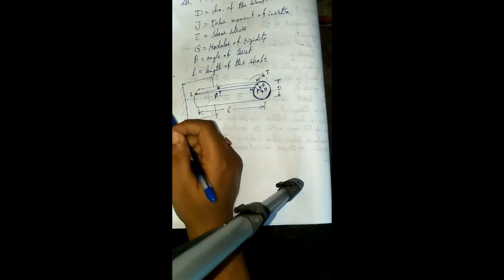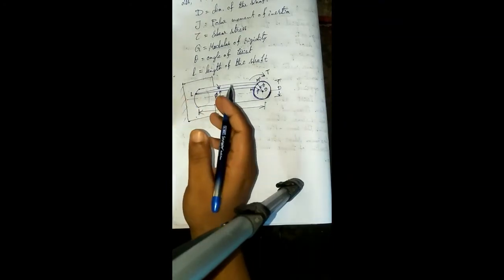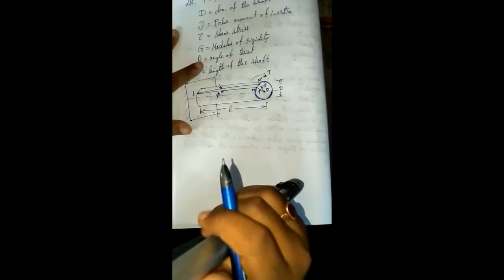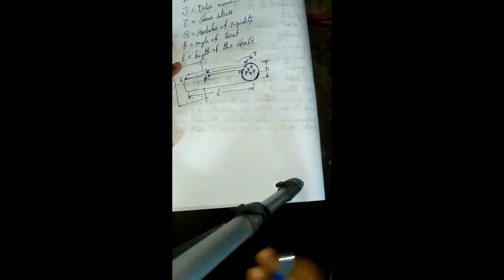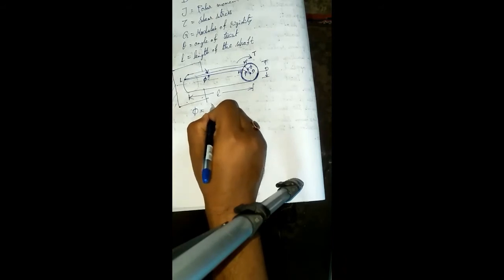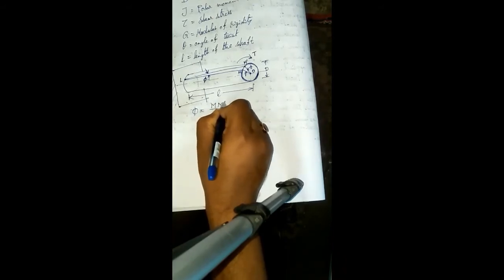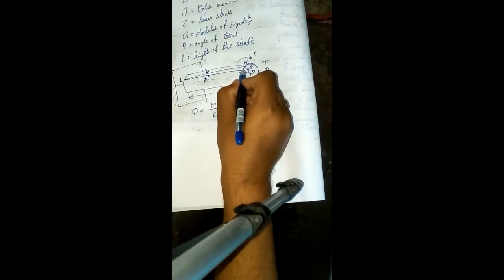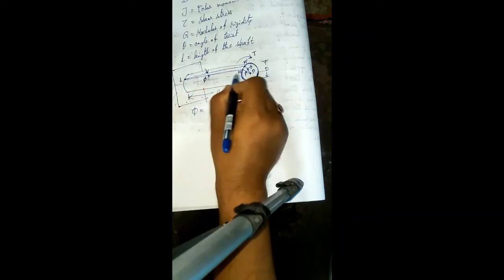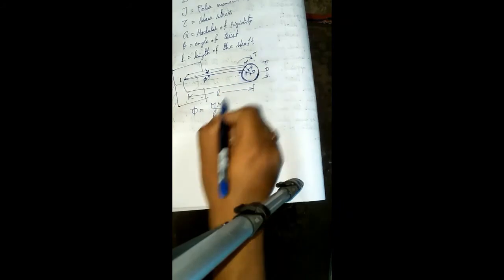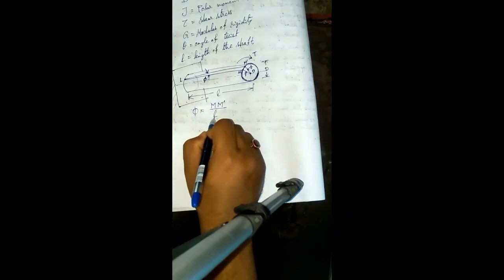So here phi is the shear strain. So phi becomes equal to M M dash by the length. This M M dash is the arc length, and this is the length of the shaft, L.